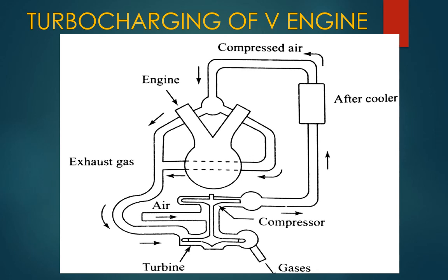So turbocharging is a concept where we do the supercharging process with the help of a turbine, which runs independently on the exhaust gas from the IC engine. Therefore, it is called turbocharging. The word turbocharging here signifies that it runs on a turbine that is powered by the exhaust gas of an engine. And once again I repeat, turbocharging is a form of supercharging mechanism. Supercharging, the word super, simply means increasing the pressure of the air, right? That is the point of it.